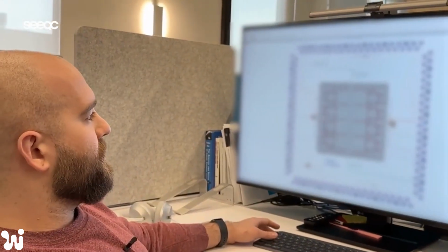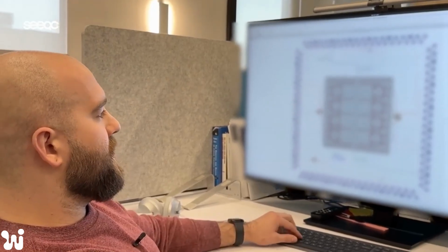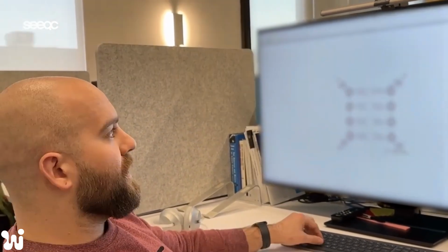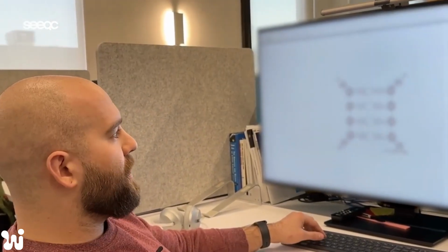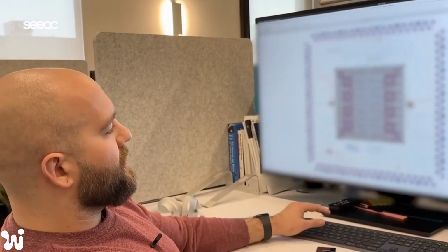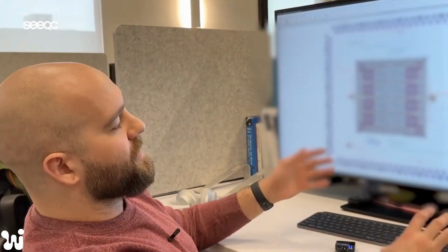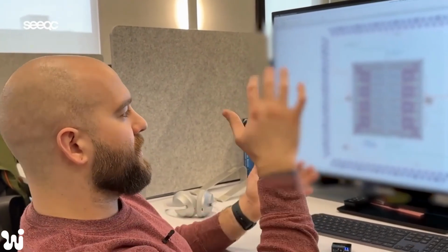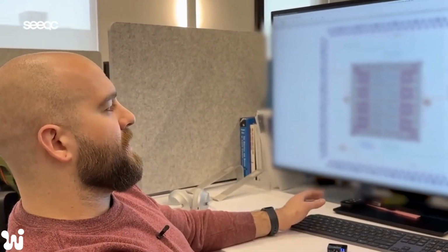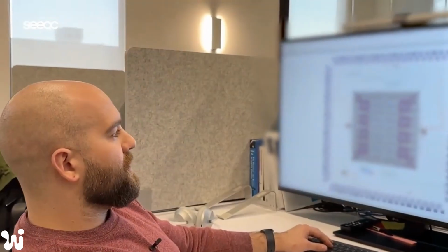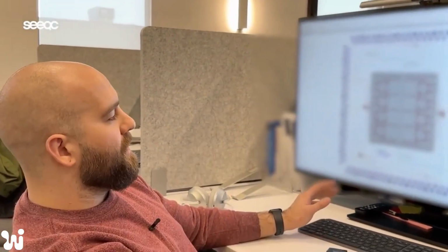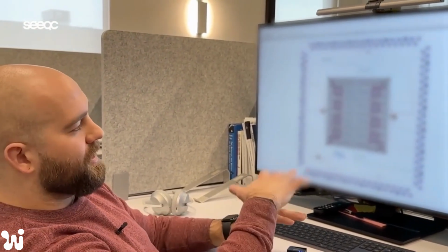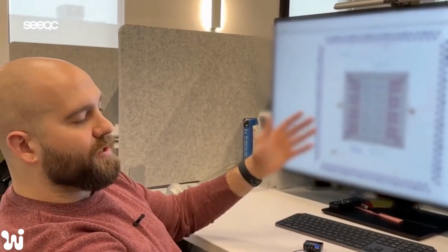The carrier chip gets fabbed in-house in our own fab, and then the flip chips we order from a quantum foundry. We receive these chips and bond them together to make these MCMs. And this is what we're currently measuring. Because it's modular, we can verify the functionality of the most complicated stuff before we take the time to assemble and potentially sacrifice a flip chip. So we can take just this bottom chip, test it at 4K, and verify that it's functioning, and then we can make a bond and actually make an MCM, and then proceed further with the testing.